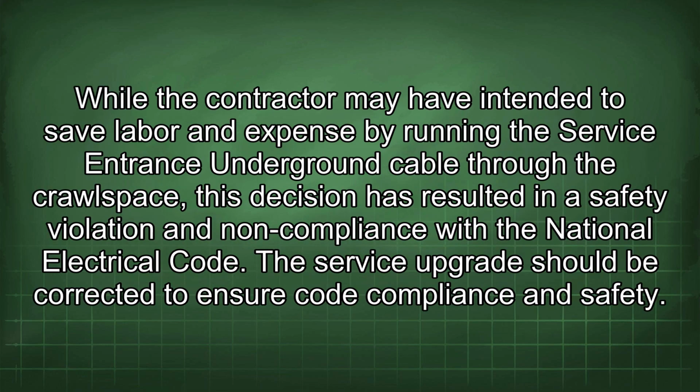While the contractor may have intended to save labor and expense by running the service entrance underground cable through the crawlspace, this decision has resulted in a safety violation and non-compliance with the National Electrical Code. The service upgrade should be corrected to ensure code compliance and safety.